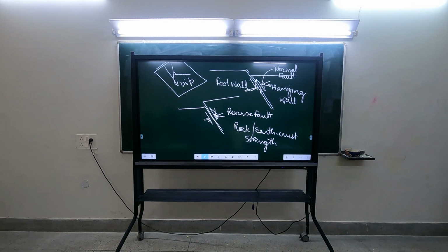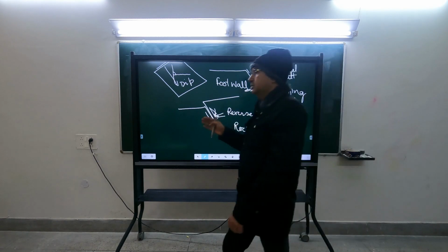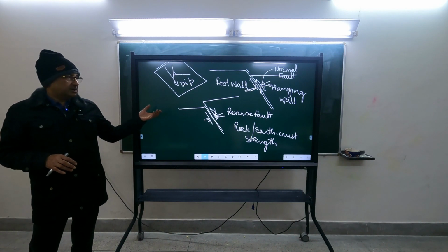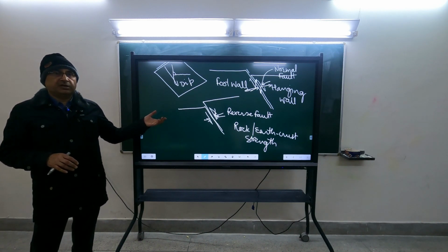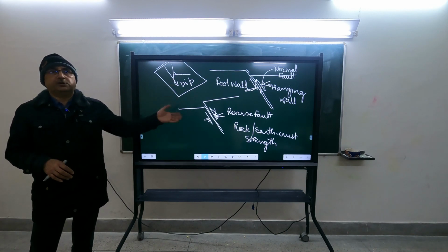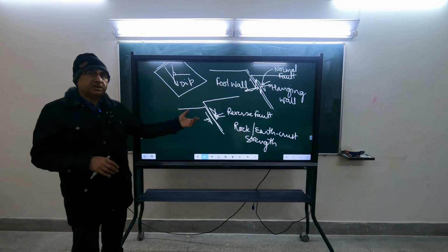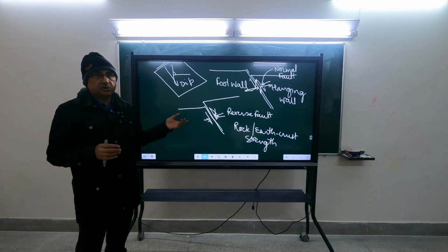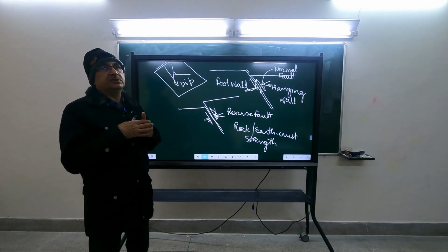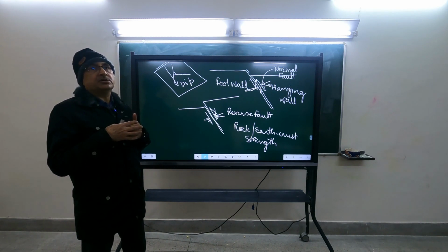When the earth crust is weaker, frequent earthquakes will occur, but the intensity of those earthquakes is going to be less. That's why the characteristics of different faults will be very different. It depends on so many things. The magnitude of the earthquake which can occur and the frequency at which those earthquakes occur will vary from place to place, fault to fault, because it will depend upon the type of the earth crust. The earth crust is not uniform throughout. It will also depend upon the stresses developing there and the rate at which those stresses are developing.